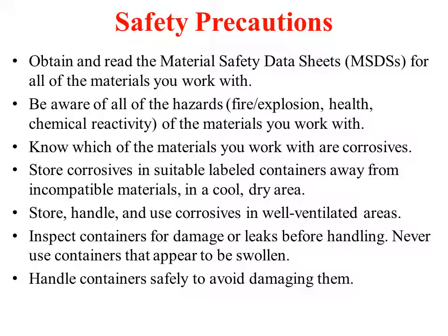The amount and type of ventilation of course depends upon the kind of job, the amount of materials used, and also the type of chemicals being used. And whatever ducts or ventilation systems are there, they should be corrosion resistant. They should not react with the corrosive material.